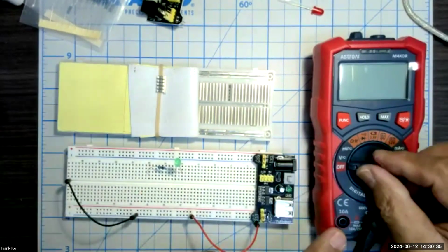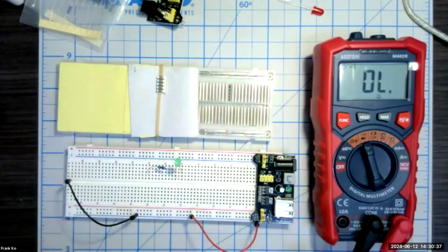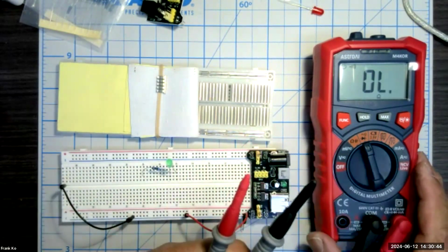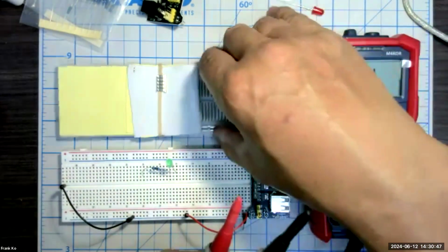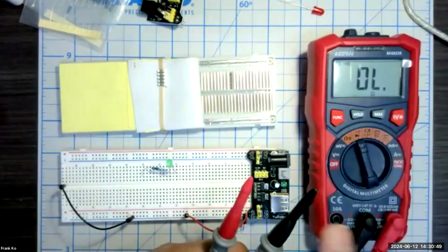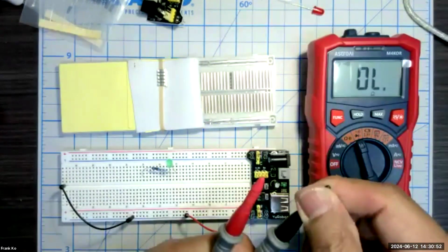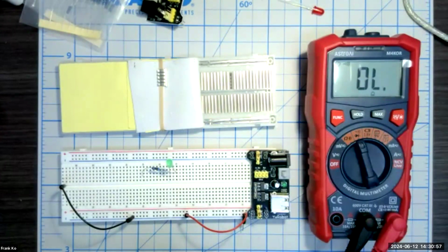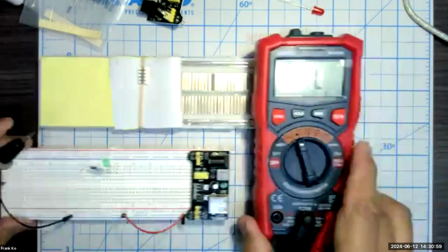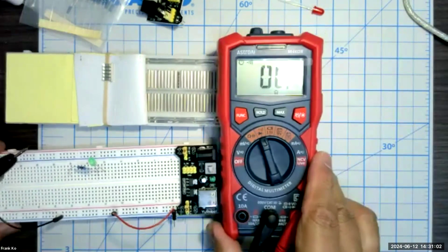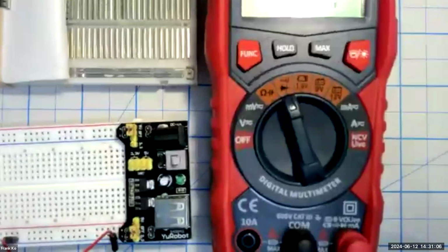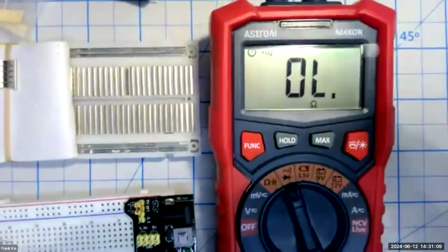This is disconnected from power, so it's completely out of the circuit. We're going to set our multimeter into the continuity test mode. We will take our test leads. Remember, anytime you test anything on the board, you want to make sure your leads are properly working. And we're going to test our test leads first. These have the protective caps. We're going to, for this moment, remove them carefully. And now listen carefully, and I'll try to do it this way so that the microphone can be in a good position so that you can hear the beep. And I'll just shut up so that you can actually hear the beep.